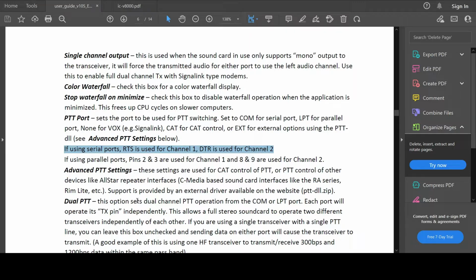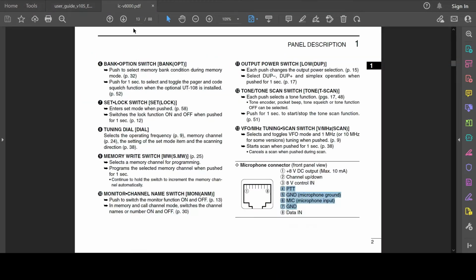Now, my radio is not a typical radio that is easy to hook a TNC up to, but I was like, okay, knowing what I know about electronics, I know how these USB serial adapters work, I know which one's the DTR pin, how can I now make this toggle my PTT button? And I realized what I needed to understand was the interface the microphone plugged into. I got digging into the user manual for my radio, and sure enough, I came across right here. And I was like, well, that just lays it right on out.